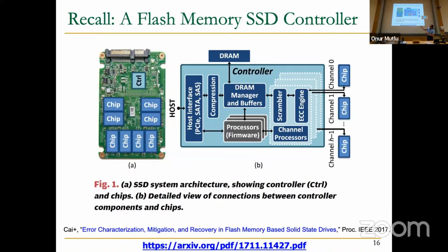And this is the host. There's an interface to the host. Host is not shown here. Host is really the host processor, let's say. And you can see that flash memory has its own DRAM so that it can do buffering of the data. So even though these are the flash chips, to control the flash chips, you need an entire system, if you will, and also other memories as well. So you can think of this as a memory hierarchy within a memory hierarchy. Like you have this entire system over here, but to make flash memory operate, you have another memory hierarchy, another system to make it work. And that's what's fascinating, actually.